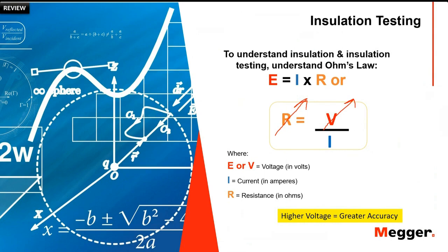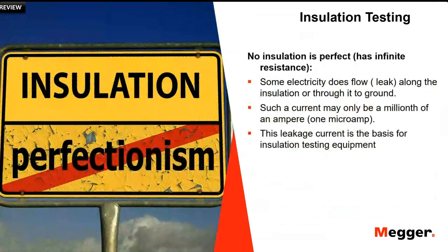We all know that no insulation is perfect. Some electricity flows or leaks along the insulation or through to ground. Such a current may only be a millionth of an ampere, so sometimes we are dealing with microamps here. Please take note, we are looking at the leakage current. This will be our basis for the insulation testing.